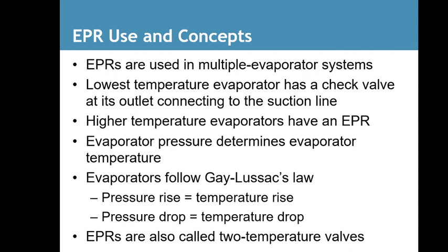EPR use and concepts. EPRs are used in multiple evaporator systems. The lowest temperature evaporator has a check valve at its outlet connecting it to the suction line. High temperature evaporators have EPRs.